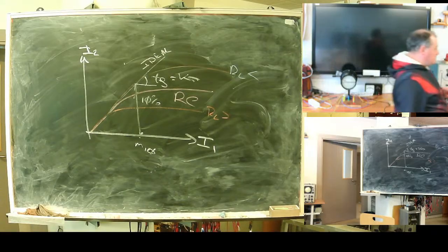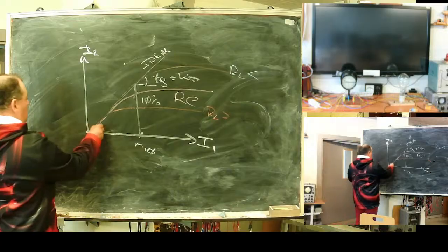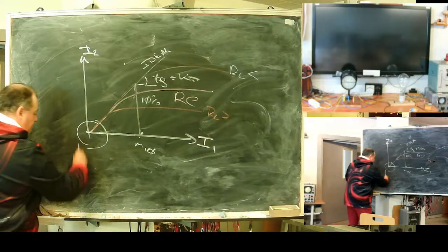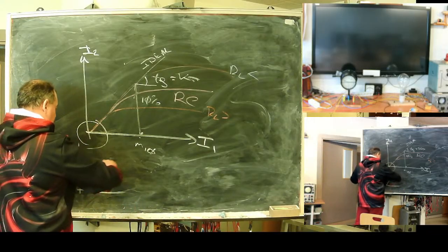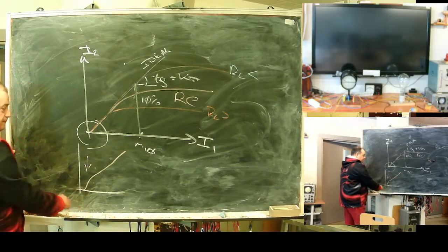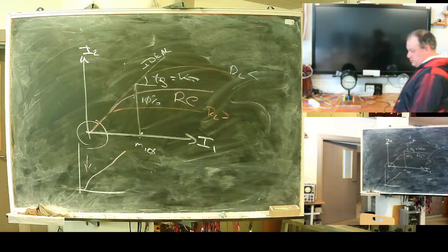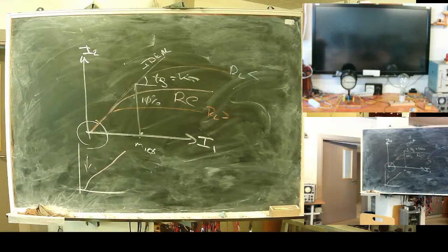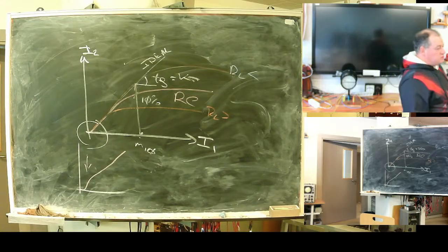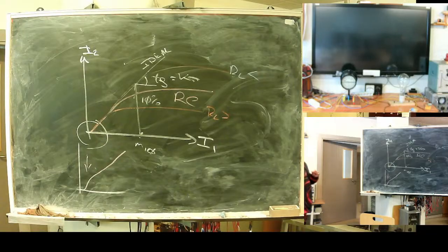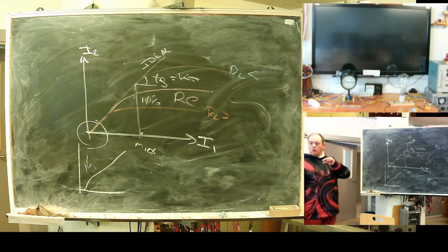Then one more moment. At the low end of the characteristic, non-linearity is also present. Even good electrotechnical steels do have non-linearity at the center of the magnetizing loop. Again, this means an increase in error at a low signal.